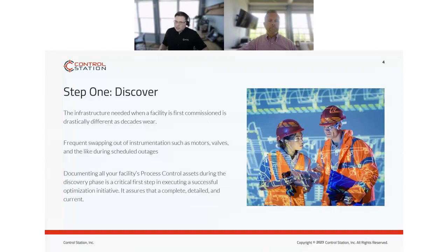I've definitely been to manufacturing sites where the expert has retired and half the people there don't even know what certain pieces of equipment do, what certain pieces of control logic do within the DCS or PLC, and that documentation was never created in the first place. So you have to spend a lot of time starting at the beginning and doing a little bit of controller rationalization, right? You have to do the same thing with alarms and events. You kind of have to do the same thing with all your controllers. What are the controllers that you have? Which ones are being used?